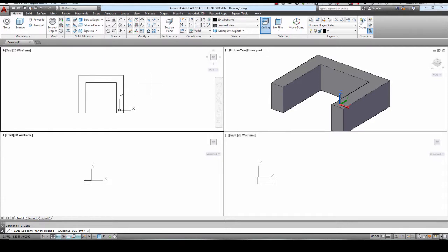So that allows me to go in here and use my offset command to offset that 1/2 inch. So I'll pick this here and offset it in 1/2 inch, and then I'll come over here and draw a line from that endpoint to that endpoint, and I want to make sure that I get my endpoints and not something else. So I'm going to click like that. So now that I have that drawn, I can come back into my top viewport and use the region command again to highlight that, and it becomes a region.